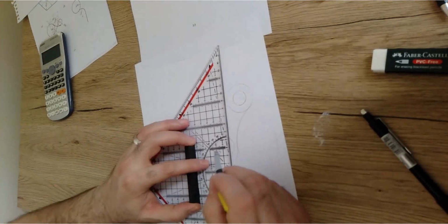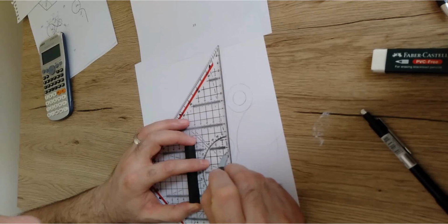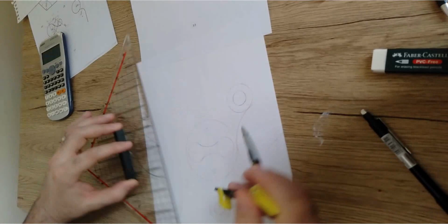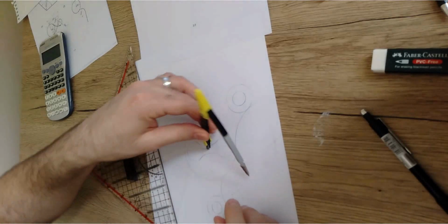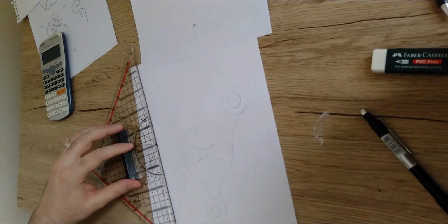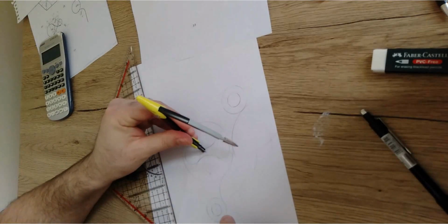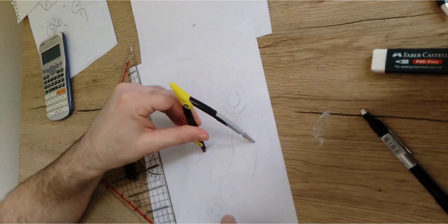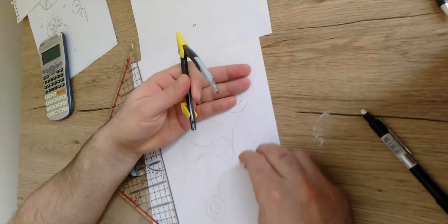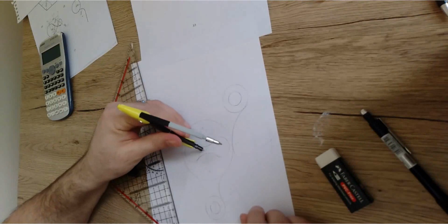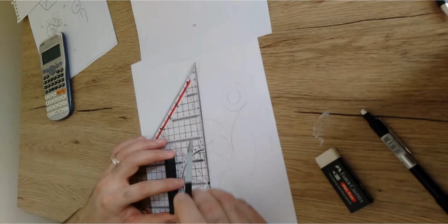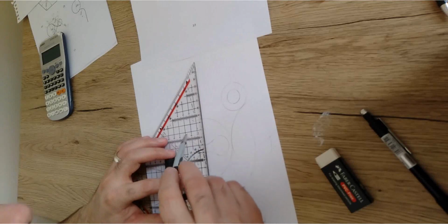So let us use the 72 from the big circle first. 72. And then I'm just going to draw a curve that should be the locus of the first tangent point. The tangent point should be on the right. Then, as you can see, it has been moved. Alright, so just to be accurate, this should be the curve. Right, with the same opening, here is going to be 72. Then on the other side, I'm going to open the compass to 97.